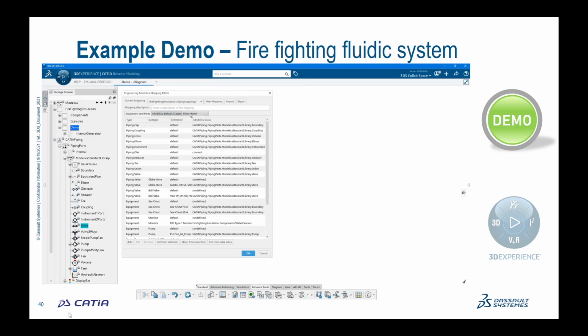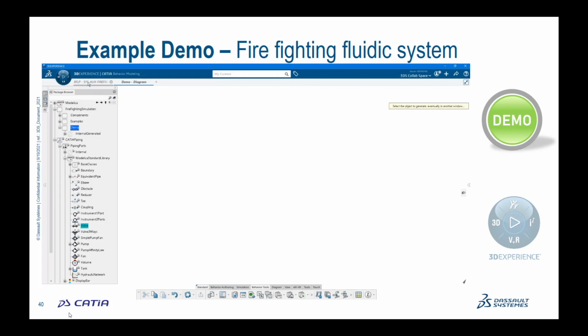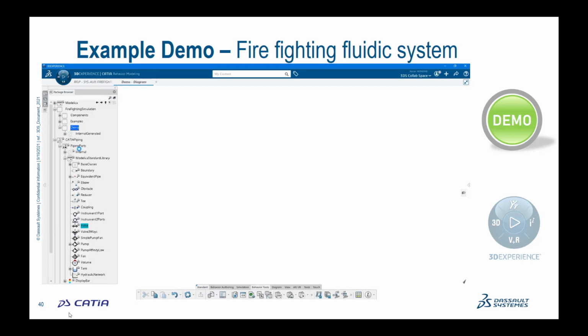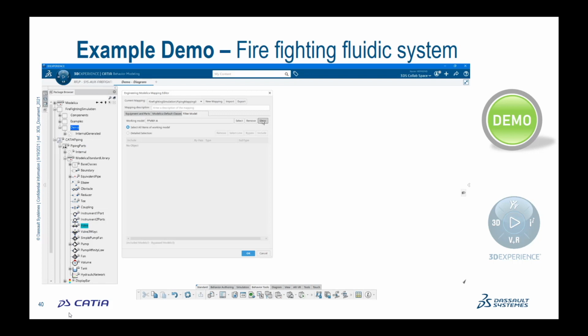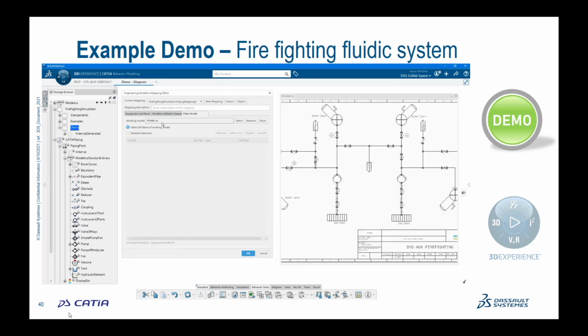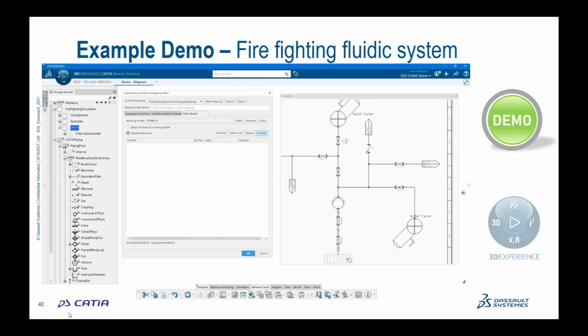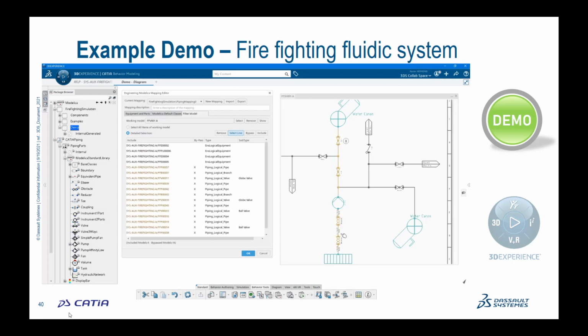Next step is to select the pieces of equipment, the piping parts and the pipes to be included in the simulation. The items can be selected individually. Each piping line can be selected in one click. In this example, some valves are bypassed and they will be represented by connections in the Modelica model.